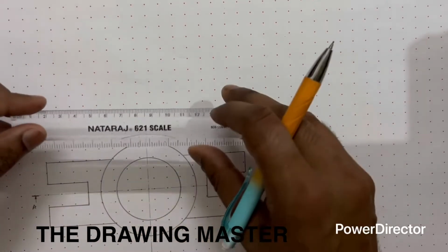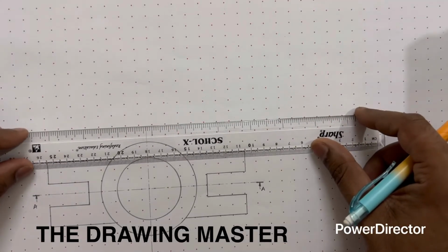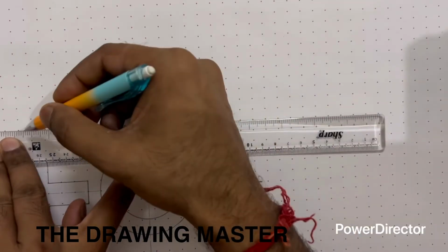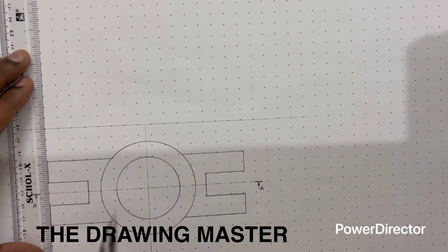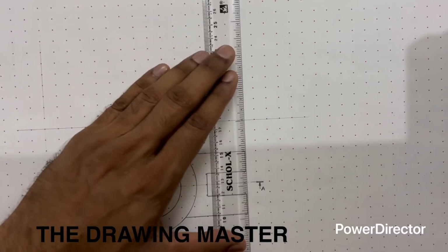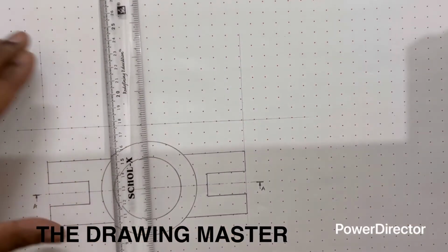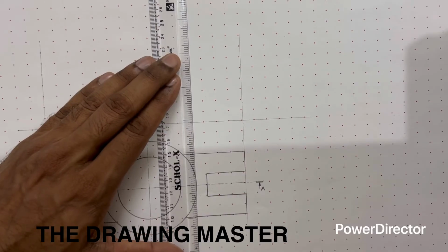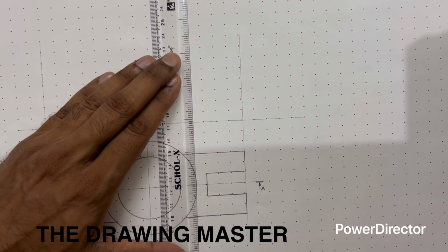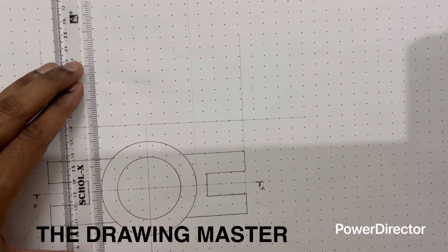So now let's take the projections by taking the reference line. This is the reference line. Let's take the projections now. So here first we have projected the length of the object. Now let's project the diameter of the object. You have to be very careful here while placing your scale. Scale should be vertical, used to draw the vertical line here. Projections should be exactly vertical.